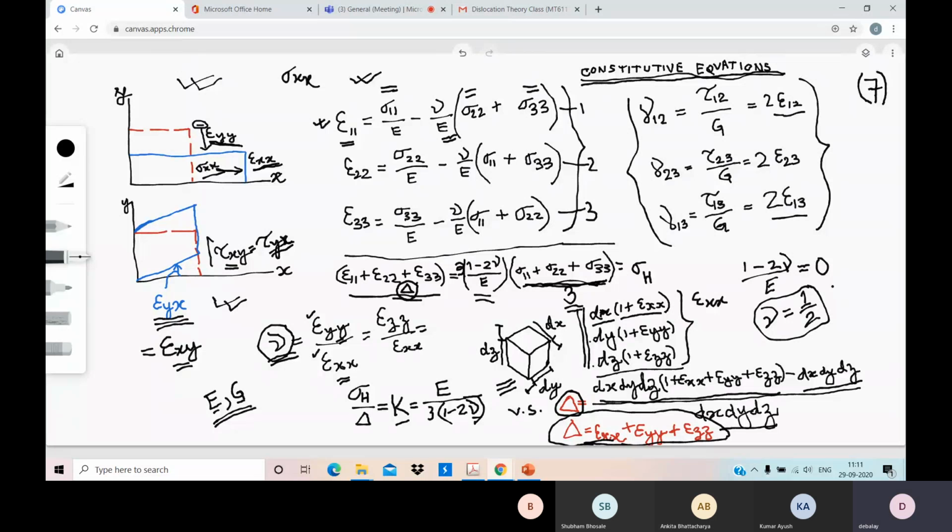So when plastic deformation happens to a tensile specimen, the epsilon YY or epsilon ZZ that you get is basically half of the amount of longitudinal strain that the specimen is elongating. So remember, under plastic deformation condition, nu equal to half, and similar expressions hold. Similar expressions hold only since plastic deformation is incremental. Therefore, instead of epsilon we write d epsilon.